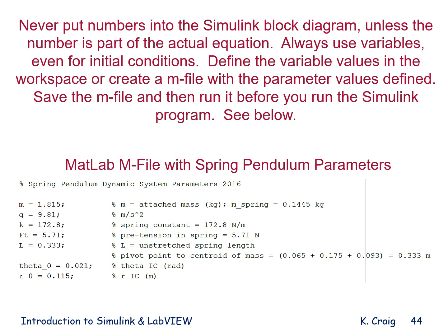So as you can see, this is my spring pendulum dynamic system parameters. Here are the parameters. I specify what they are as well as the units associated with them, because MATLAB Simulink does not keep track of units. If you mix units, well then MATLAB and Simulink will not pick up the error and your answers will be incorrect.